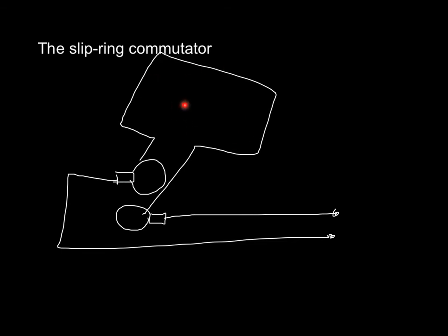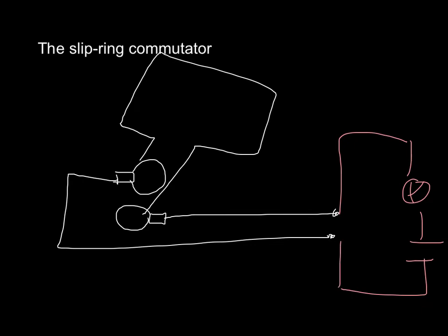Now as this rotates, these things rotate along their ring. So this is connected to here, rotates with its ring, keeps going like this. This thing is here, rotates with its ring, keeps going like this, which ensures that the potential difference here is transmitted to the potential difference between these two wires, and therefore between here and here. And then here I can just connect whatever circuit I please with light bulbs, capacitors, whatever I want, and it will work fine. So again, the idea is I connect each of these two things to a ring that can rotate freely next to a brush, and then the potential difference between these two places that's generated by the magnet will stay between here and here.